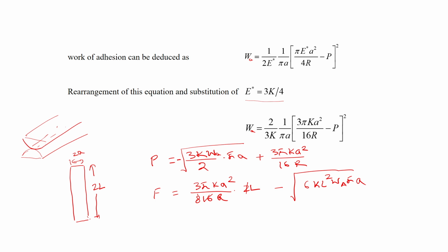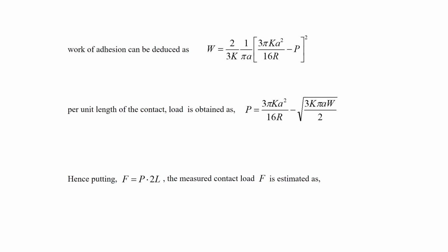So, in the experiment I will measure basically F, and we will measure a here, and then we can arrange this equation to obtain the work of adhesion and the elastic modulus, this quantity K here. Remember that we did it for JKR contact mechanics, where we did the same thing.